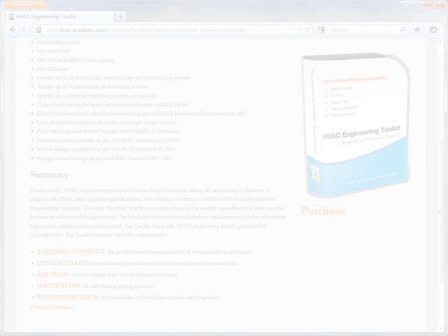In order to provide individual space temperature control, the terminal hot water reheat coils located on the duct runoffs to each space shall increase the supply air temperature maintained by the air handling unit during part space cooling load conditions. Perimeter hot water baseboards shall be located along exterior walls to compensate for the heat losses through building envelope in winter. The reheat coil and baseboard shall be controlled by space thermostat. Air diffusers, not shown in the schematic, shall distribute the air throughout the spaces from the ceiling level.